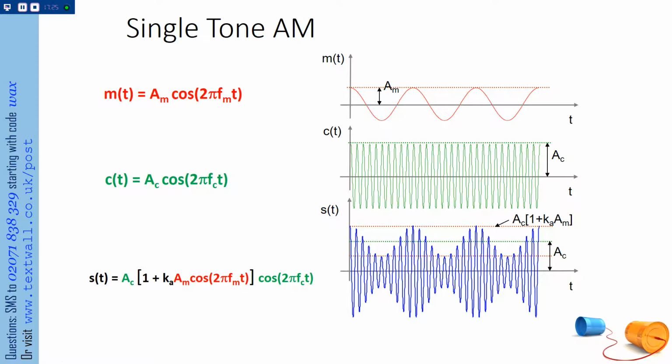And after adding that constant, 1, we then multiply it by the green signal. So you shift it and then multiply it. That way, we have this envelope that doesn't equal 0. The envelope is always positive. All right, so this is mathematically what happens inside an AM modulator.